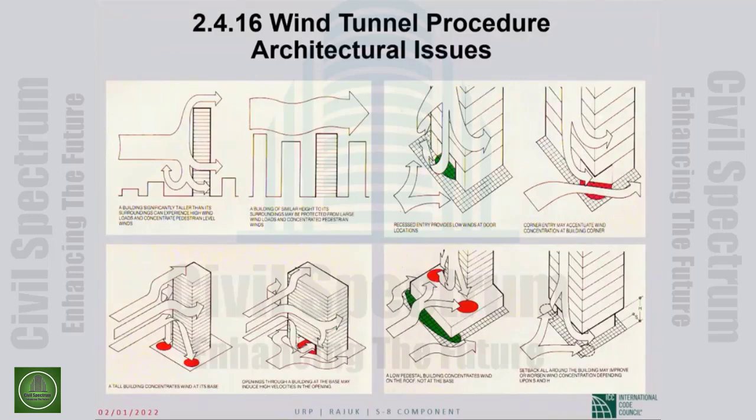There are times when you go through two tall buildings or even enter a tall building, you feel the wind. If you have loose clothing on, the clothing wants to come off. There is pedestrian comfort, people who are walking around tall buildings, and all of those things can be figured out beforehand, before the structure goes in place, by proper wind tunnel testing.